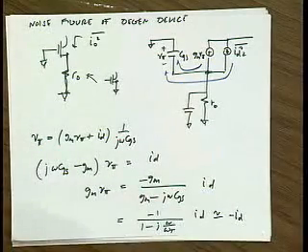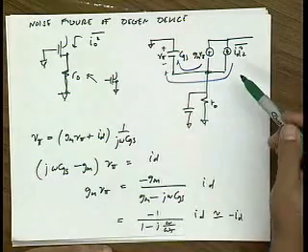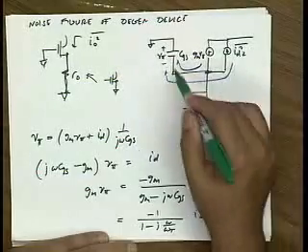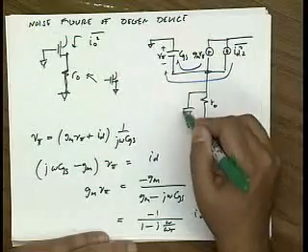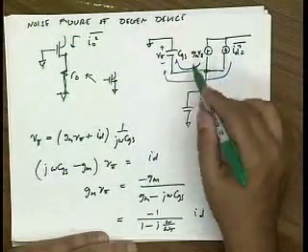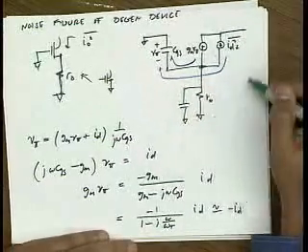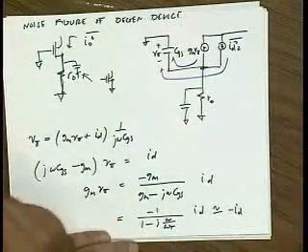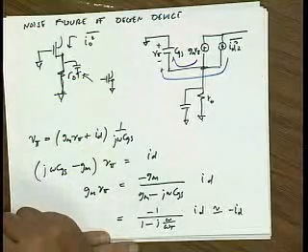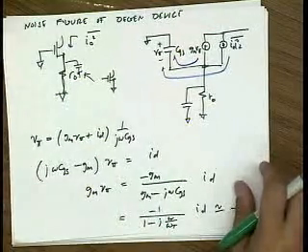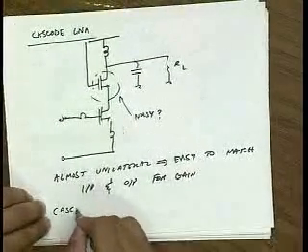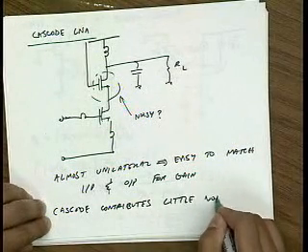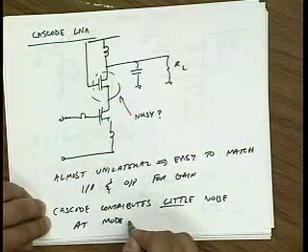There's a couple of interesting points about this perspective. This tells you that at really high frequencies, the amount of current that goes here is not necessarily all the current. Some of it will go through this capacitor. And as current goes through this capacitor, the amount of cancellation is reduced because this current will flow back into your load. So at really high frequencies, we'd like to minimize the capacitance on this node in order to minimize the noise contribution for this device. Okay? So coming back to here, we see that the cascode contributes a little bit of noise, let's say at moderate frequencies.